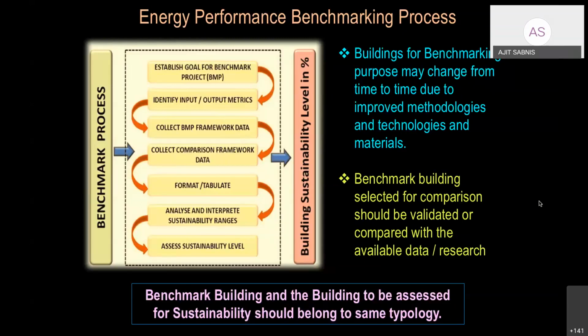The benchmark building and the building to be assessed for sustainability should belong to the same typology. This is another important parameter to be considered. That means I can't use a benchmark project taken for, let us say, a commercial building as a benchmark for assessing a residential building or some institutional building. So this is what it means: the benchmark building and the building to be assessed for sustainability should belong to the same typology. These important factors are to be kept in mind for the benchmarking process.